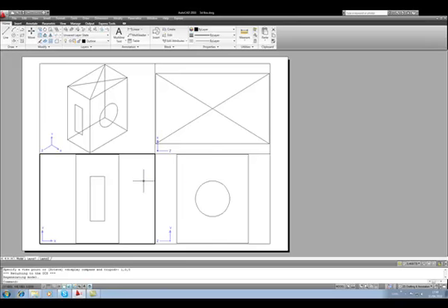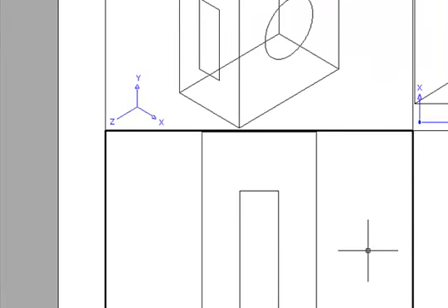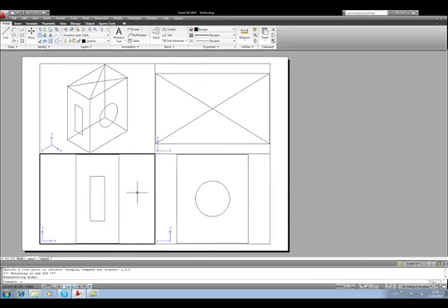I'm now going to use the ZX command, the Zoom X command, to resize the views in each of the viewports to make them fit better. So with the bottom left hand viewport selected, type Z, enter, 0.75x, enter.